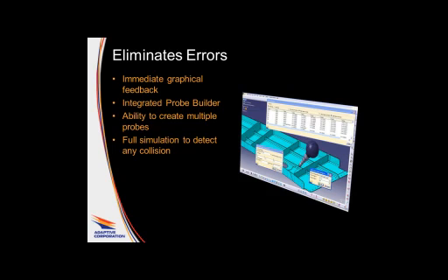Since you are working inside a CATIA product, you have the ability to have any holding or NC fixture included in your CATIA model. This typically is not done when using IGES or importing the IGES into a CMM software application. The reason why is because CMM software applications are not typically a CAD system and will not handle such large CATIA assembly models.